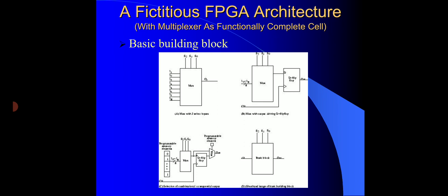This also includes the number of cells; if more cells are divided across this FPGA, it can provide more configurability. The routing interconnect of these FPGAs is generally steered by smaller multiplexers, and the basic blocks of these multiplexers have a programmable memory element that is used to implement the logic functions.